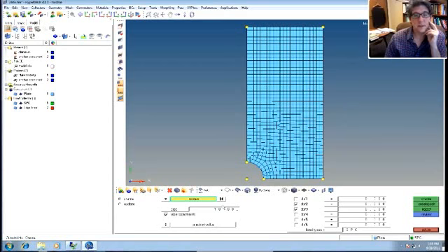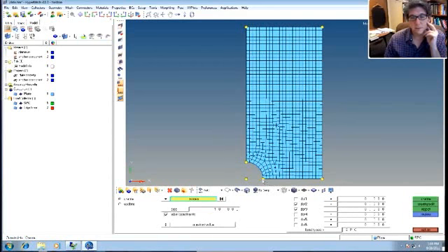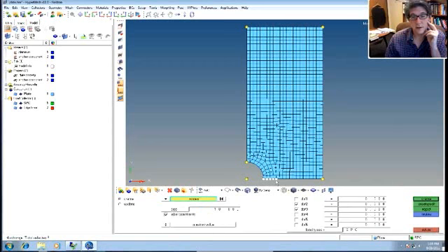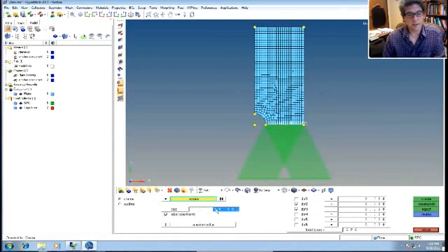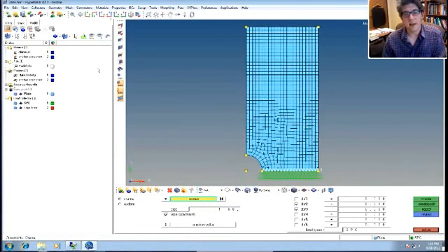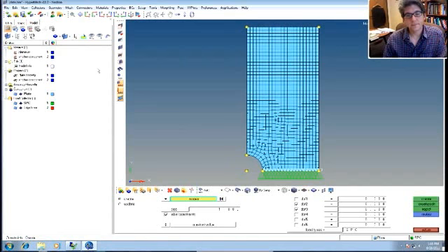Okay? Now we pick the nodes. You can just pick them one by one, or you can pick by window. A nice feature is actually you can do pick by path. I kind of like that. It allows you to pick a start one, and then an end one, and it picks all the ones in between. Okay? So now we can create those, and it draws them as little triangles. See, they're a little big, so I can make this actually 1, and that controls the size of them. It doesn't have any effect on their values, it's just so it looks better on the screen. Okay, so we've created those, all right?